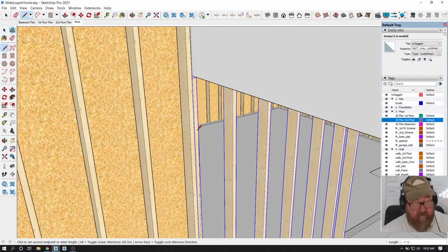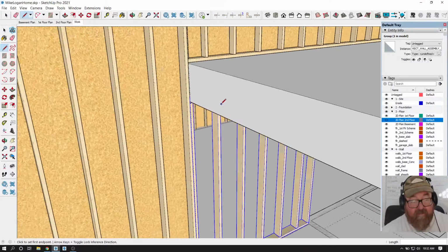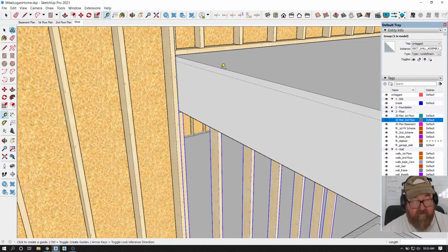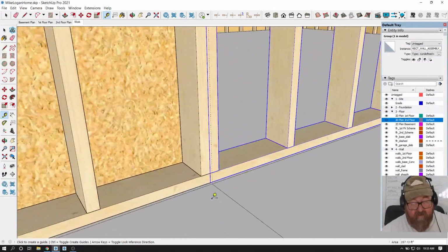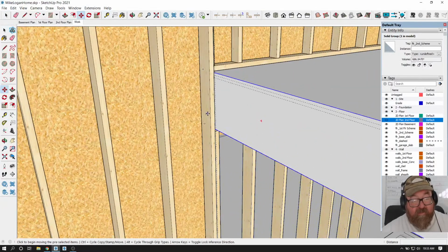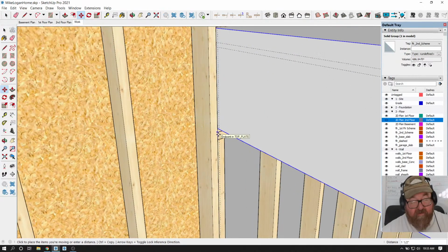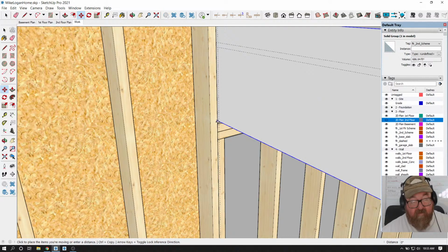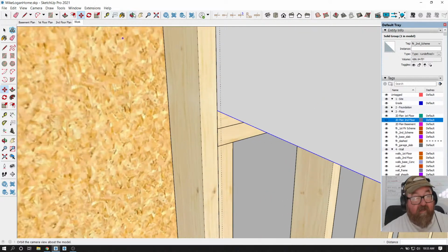How did that get there? That means this floor, I think, is this floor. This floor is going to be 16 and then 1.5 inches. Yeah, that's right, because you have 3/4 of subfloor, and then you'll have 3/4 inch of hardwood floor. So for some reason I've got this volume, this schematic floor, which will turn into a joist in a little bit. It should be moved up. And see, that's what this modeling does for you. It helps you plan correctly.